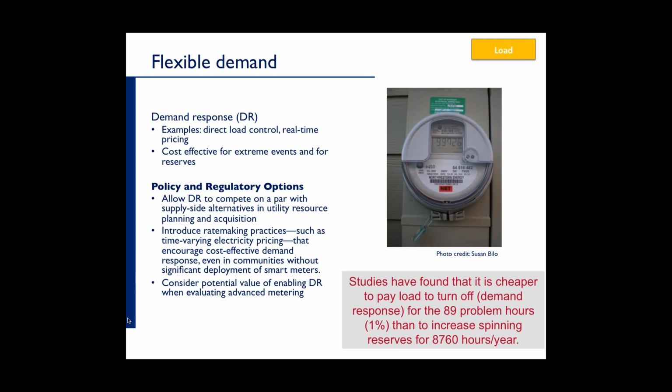We have an example in Texas here in the United States where a number of industrial units are paid to provide contingency reserve. If a generating unit trips offline or a large transmission line trips open, these industrial processes can quickly reduce their demand, which from the point of view of the power system is kind of like increasing output from a generator.